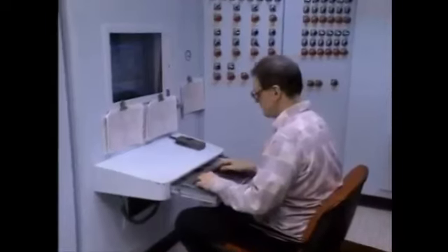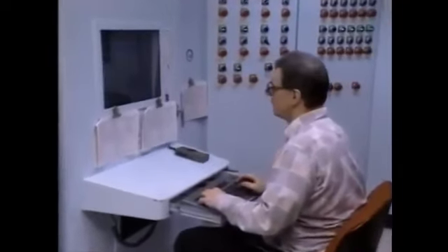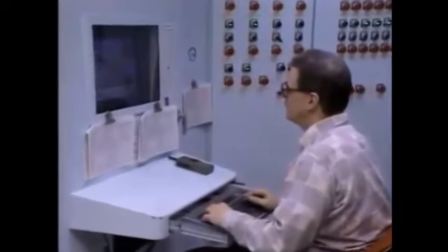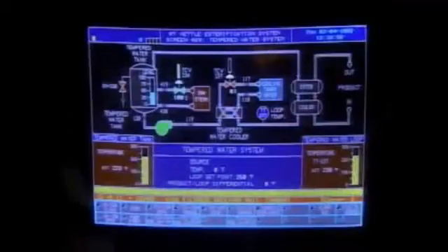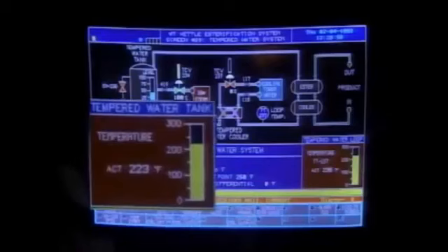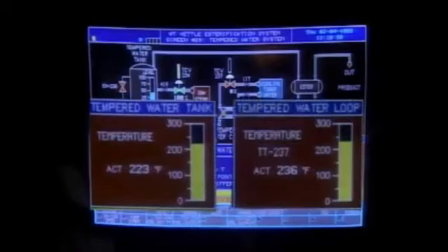By checking a heat exchanger's temperature instruments, an operator can tell how the temperatures of the fluids change as they pass through the unit. These values can also be used to determine the difference in temperature, or delta T, for each fluid. The delta T can be used to see if the unit is operating properly.